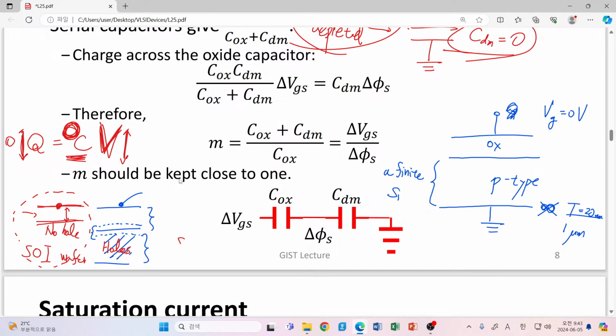So why is it called SOI? This is nothing but silicon on insulator. So how can we make a silicon wafer? We just make a silicon ingot and slice it. This is a relatively cheap process, because we have bulk silicon and just slice it and polish the top surface and bottom surface, and that provides us the usual silicon wafer.